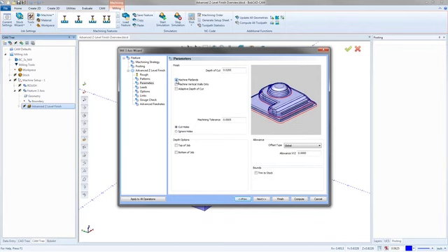The machine flatlands, this is going to go in and it's going to match the final cut. So one final pass is going to cut all the way to the floor level so you can blend that floor and wall together. The big thing with that is a lot of times it's all about the ball mill you're using when you're trying to blend it. If you go too big, the radius that's in there is just too big left in the corner. And if you go too small, well, there's really no too small. If you go too small, you just can't cut as much. So you take more time. So machine flatlands is a good one for just getting a final good cut where it's just going to match the floor depth and then make it a little easier, hopefully, for you to blend into that floor.